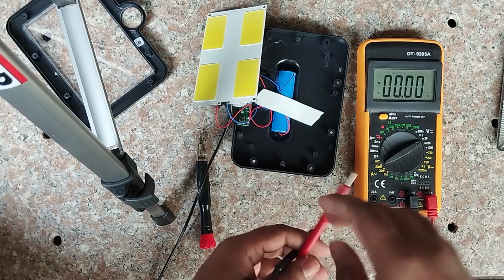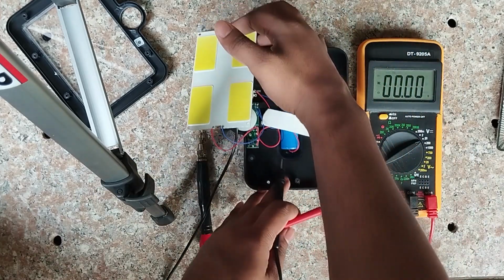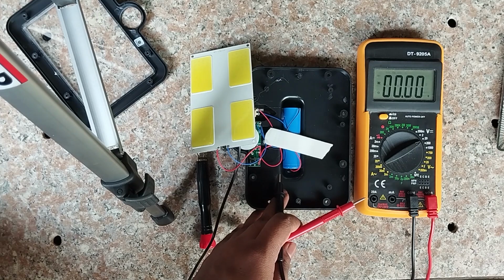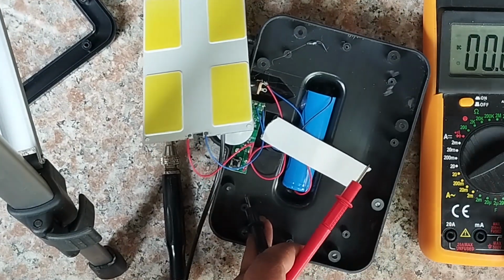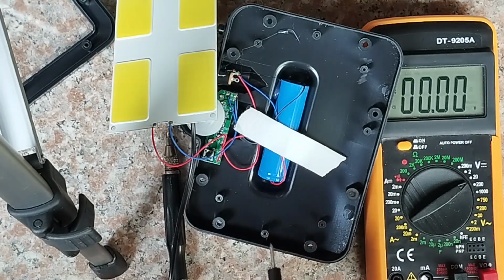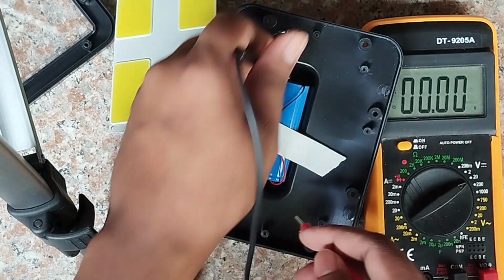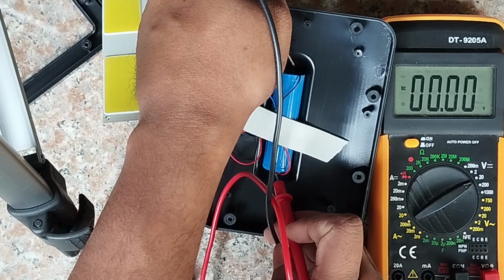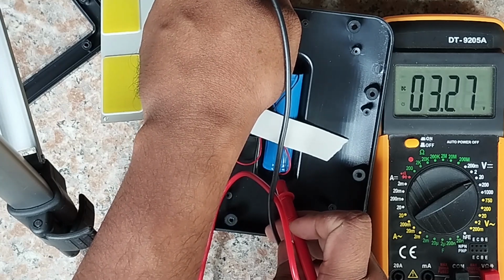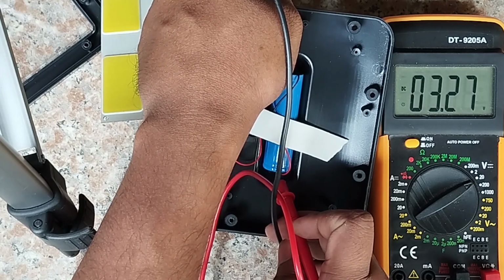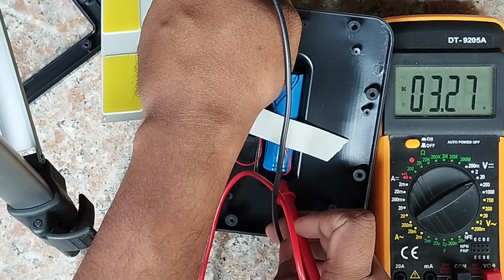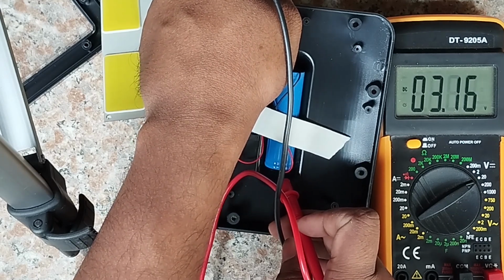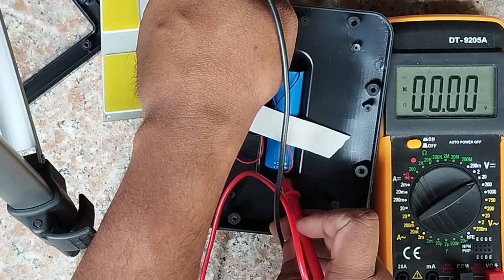18 means 4.18 input voltage, and the maximum voltage for charging a single lithium-ion battery of this type is 4.2. Then the camera view is much closer. The battery is at 3.27 volts while charging, which means the battery was drained the previous day. That is no surprise, and the LED panel is always energized.